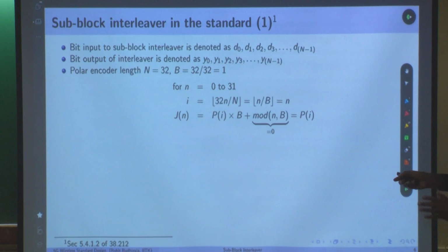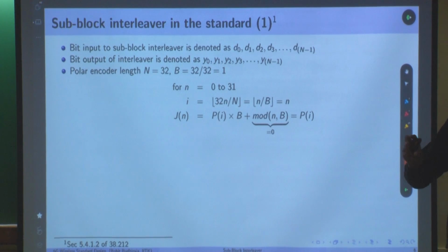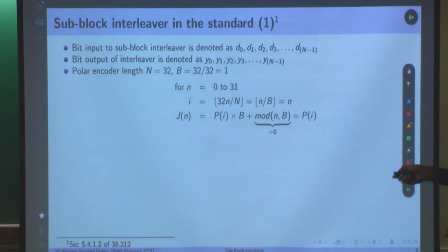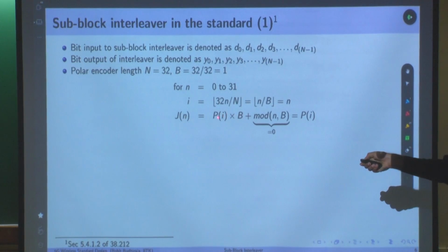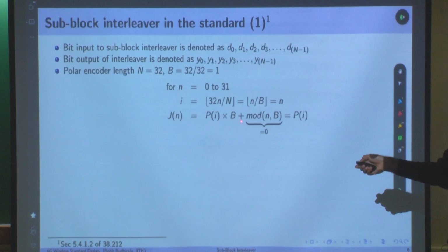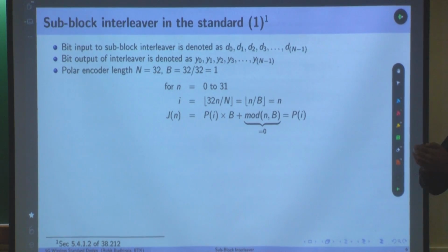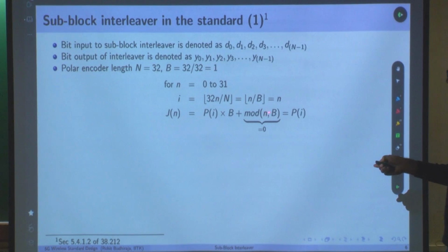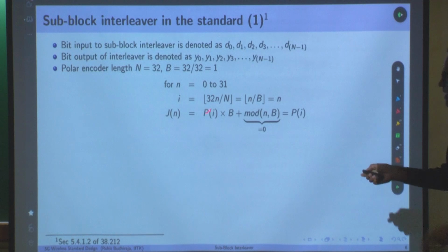So this is again, what is happening, only a 32-bit pattern is defined, okay, and as I said, this interleaver operates on only 32 bits at a time, but what about the next 32 bits? It will do the same operation, but the indices are generated accordingly, that's all, okay. It will get multiplied, right, you see this p of I plus into b, what will happen? Indices are doubling, right, and then according to whether n is even or odd, 0 or 1, it will take that value. So suitable indices will be generated for a higher length sequence, that's what this is doing.